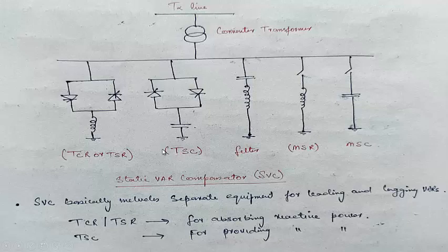Usually you might have read in your power electronics classes AC voltage regulator with resistive load or RL load, but here we have a purely inductive load and a purely capacitive load. So for an AC voltage regulator, when we want a controllable current for a purely inductive load, the firing angle will always be from 90 degrees to 180 degrees, and from 0 to 90 degrees it will lose its control.